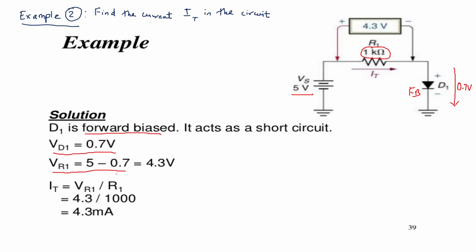5 volt minus the potential barrier, 5 volt minus 0.7 volt, 5 volt minus the opposing voltage. So 5 minus 0.7 volt is 4.3 volt. Here also you can see the meter is showing you 4.3 volt across the resistor R. Now if you want to find the total current, then the current according to Ohm's law, as we have seen earlier also, has to be equal to the effective voltage upon resistance. So the effective voltage is how much?